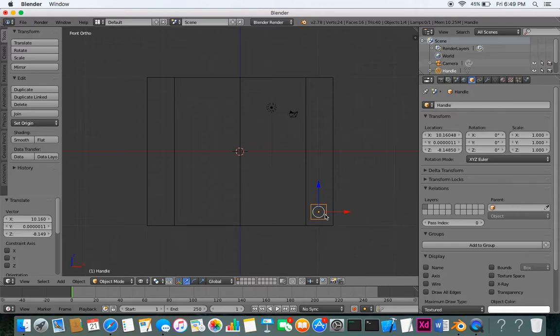Afterwards, what I will do is rotate this object. If you remember, there are 3 operations: grab, rotate, and extrude. Grab, you press G. Rotate, you press R. Extrude is basically extending. I press E. First I'm going to rotate this by 45 degrees. So I press R, 45, enter. And that just rotates it a little bit.